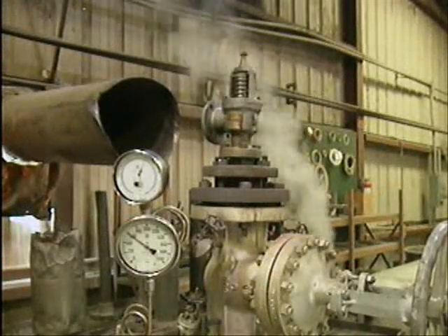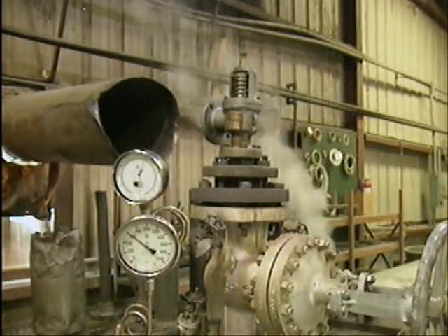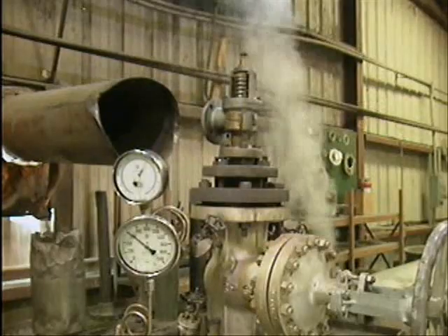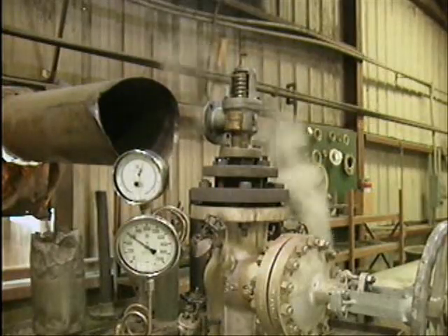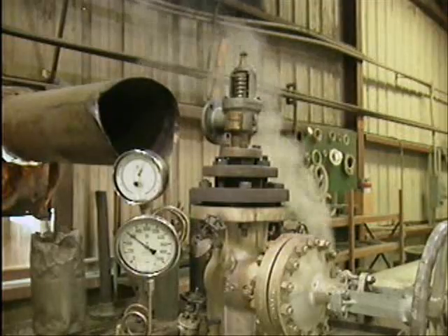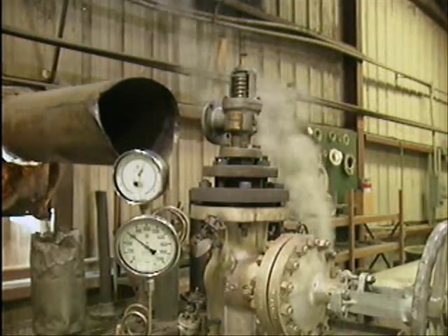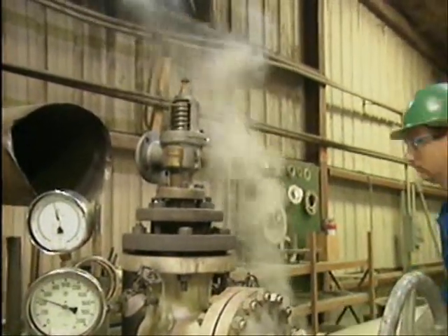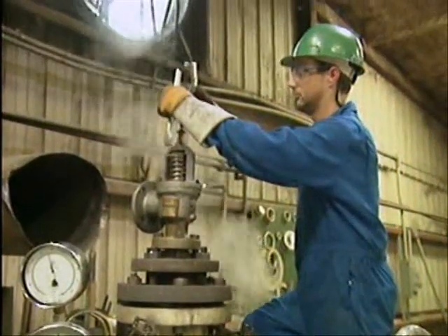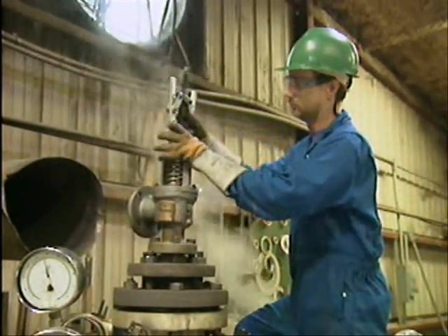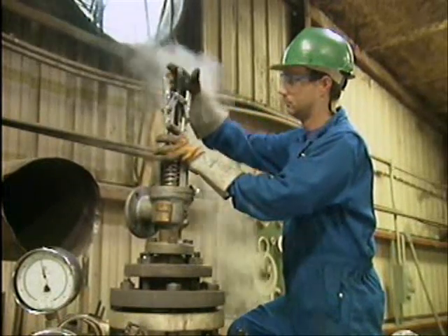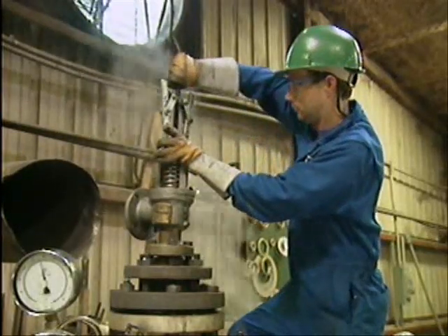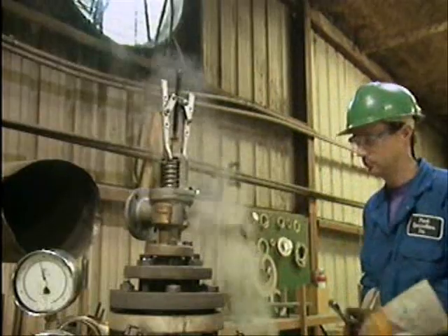Safety valves may also be affected by hydrostatic testing that's done on the system or equipment that the valves protect. A hydrostatic or hydro test is done to determine whether or not the system can tolerate excessively high pressure in case of an emergency. It also helps you detect leaks. Hydro tests are often performed at system operating pressure and below safety valve set pressure. But in some cases, during hydro testing, system pressure is raised above the normal popping pressure of the safety valves in the system. Then, gags must be installed on the valves before the hydro test is begun.